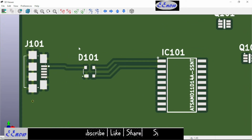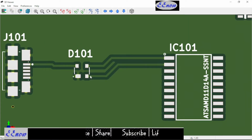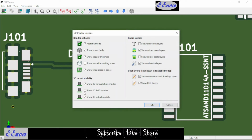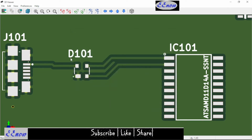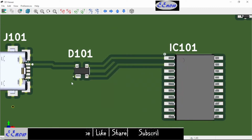But now, you see this silk screen right here? I don't know, this one looks too small or something, right? The dot. And the line looks too small. Let's change that, right? Okay, let's go back. Let's put the part back. So how do we get this menu? We click right here, right? Set display options. Okay, click there and show 3D models. Okay, showing back, right?